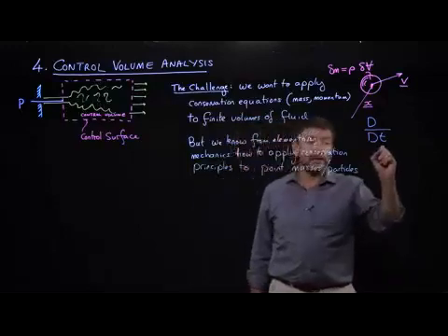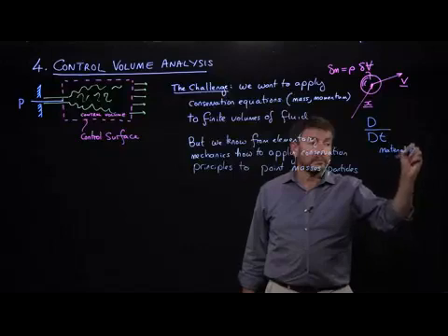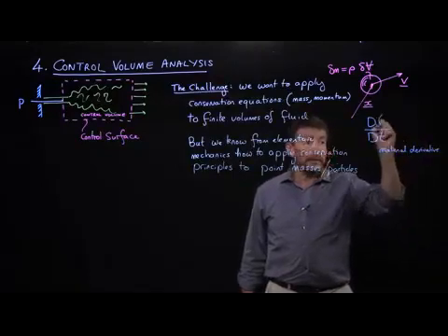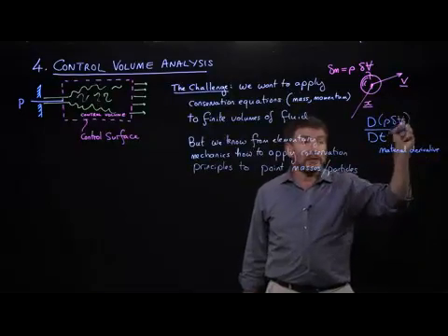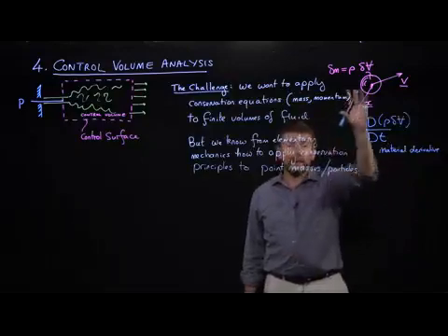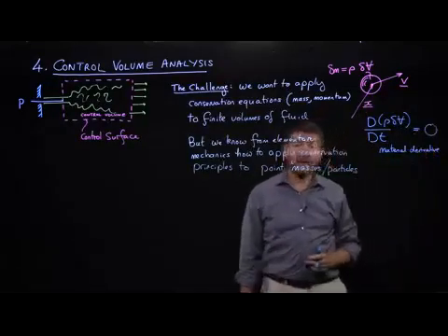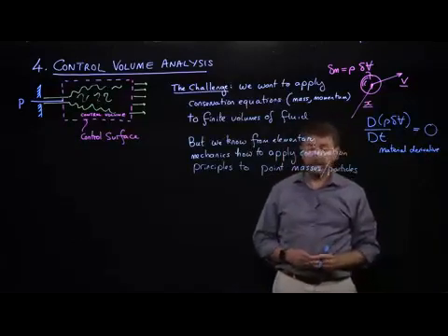So this is our idea of a material derivative. And so we might write down that the time rate of change of mass can be expressed in terms of this, and we've already derived a result from that. And essentially we've said that there is no creation or destruction of mass following that material element.